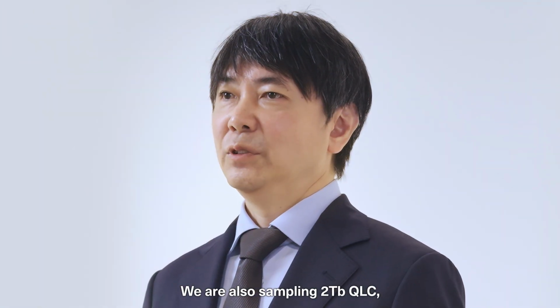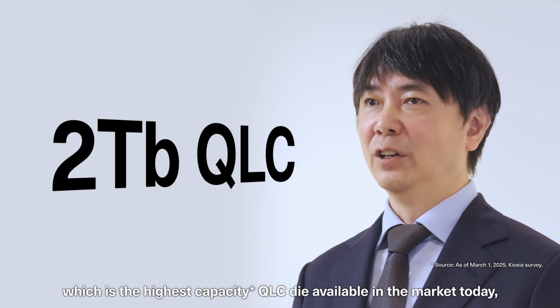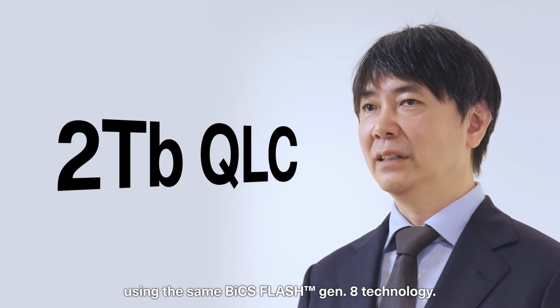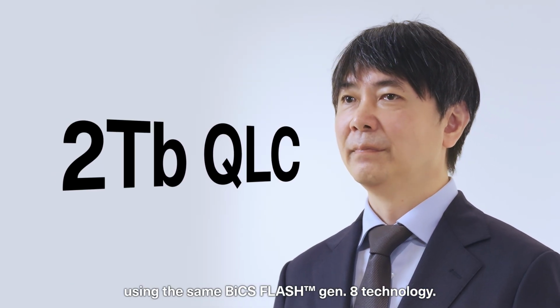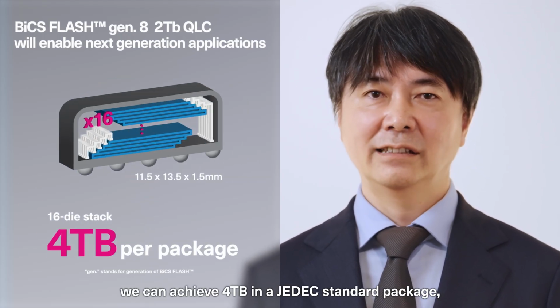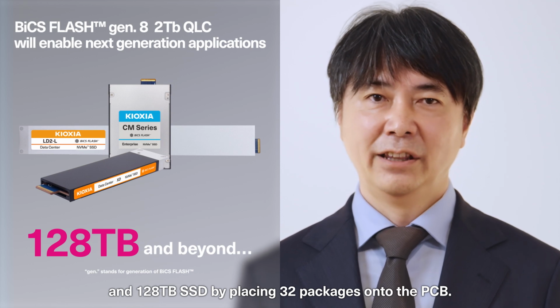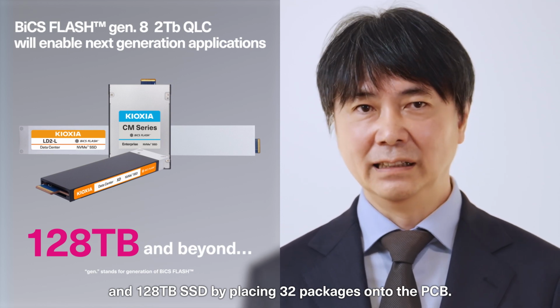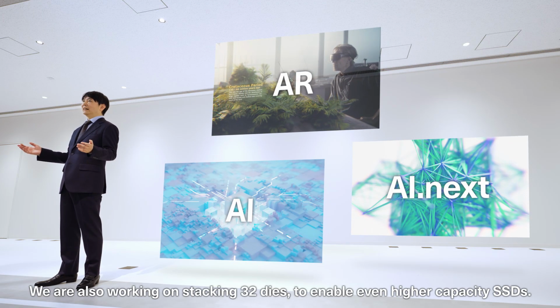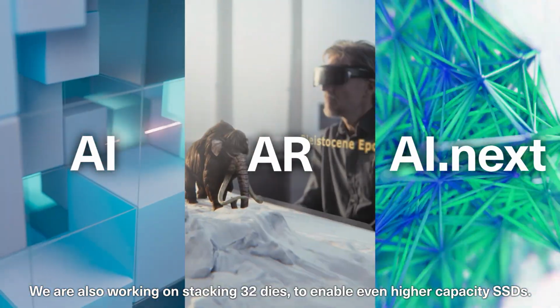We are also sampling the 2TB QLC, which is the highest capacity QLC die available in the market today using the same BiCS Flash Gen 8 technology. By stacking 16 dies, we can achieve 4 TB in a JEDEC standard package and 128 TB SSD by placing 32 packages onto the PCB. We are also working on stacking 32 dies to enable even higher capacity SSDs.